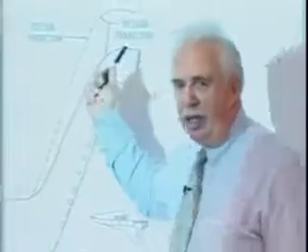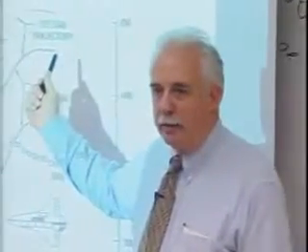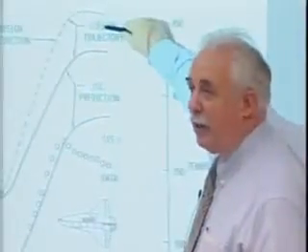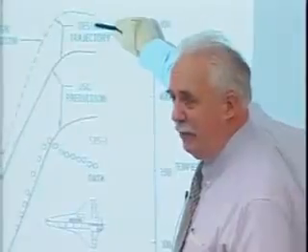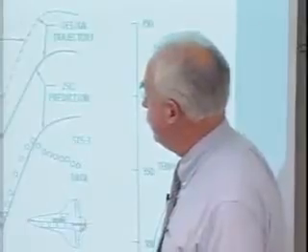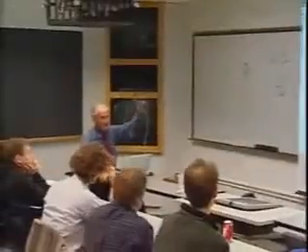Okay, this is the design trajectory coming in from polar orbit. Our design condition was we do not exceed 350 degrees Fahrenheit if we want to have 100 flight life with this aluminum. Aluminum is great stuff because it's a good conductor, but it's low temperature, expands. Those temperatures are much lower than you see on the surface of the tiles. That's after the heat has diffused.